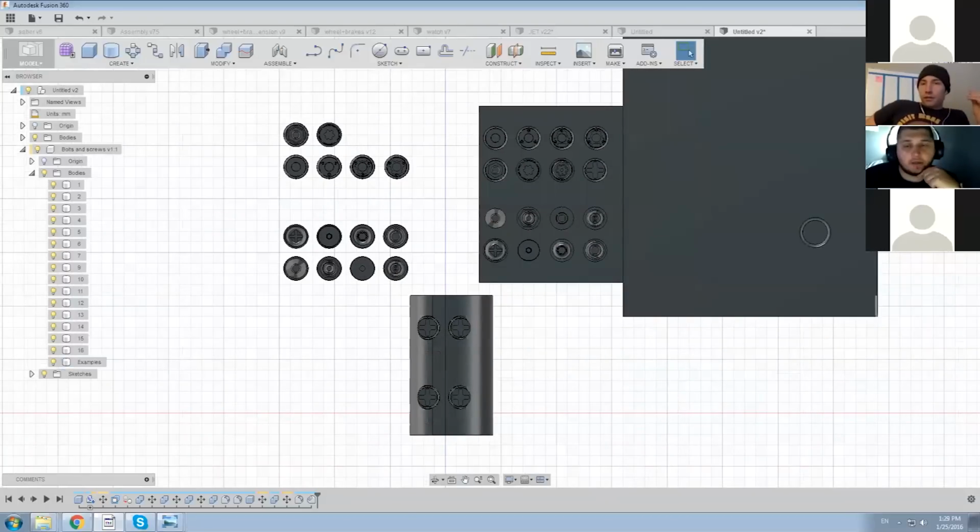For Keyshot, no conversion is required, so Keyshot eats any type of file. So you keep it in CAD, and that's how you preserve all the curves and all that. Basically, you have a T-spline body in Fusion, and you have that same T-spline body or solid body in Keyshot. So that is seamless. But for ZBrush, when you're exporting an STL, you can control the level of detail that you get out of it. But like I mentioned before, for Max, the best way is probably to export CAD and use the tools inside Max to convert to poly.